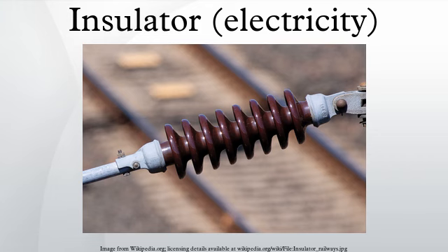Steatite mountings are used. They have to withstand not only the voltage of a mast radiator to ground, which can reach values up to 400 kV at some antennas, but also the weight of the mast construction and dynamic forces. Arcing horns and lightning arresters are necessary because lightning strikes to the mast are common.